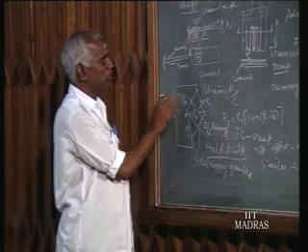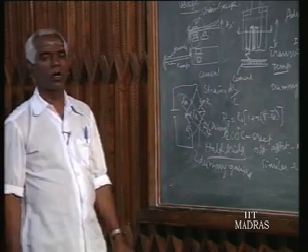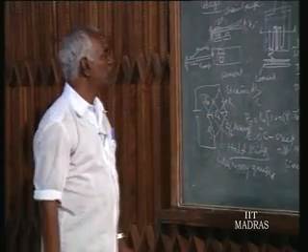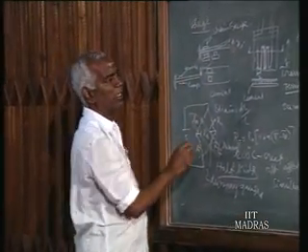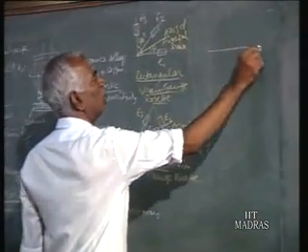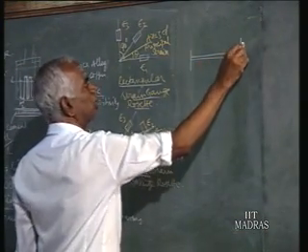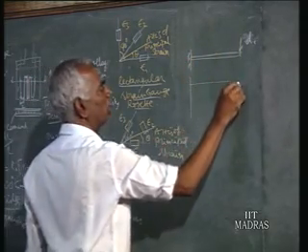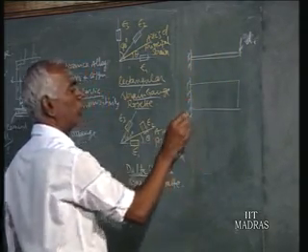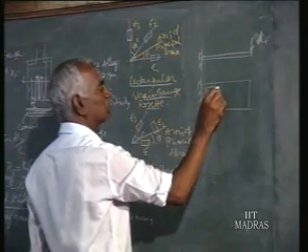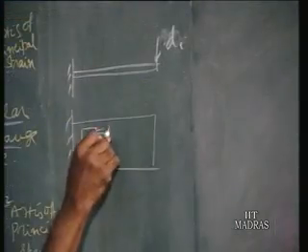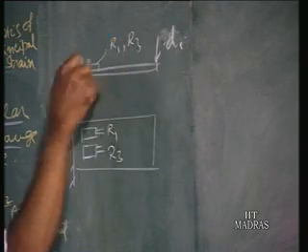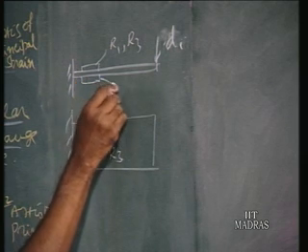So in case of the similar strain, we have to use the other two arms as the dummy arms and connect them accordingly in the bridge network. If it is a full bridge, so that is in the cantilever. So suppose this is the cantilever. This is the displacement given there, and suppose this broad sheet has two strain gauges, R1 and R3, one behind the other.